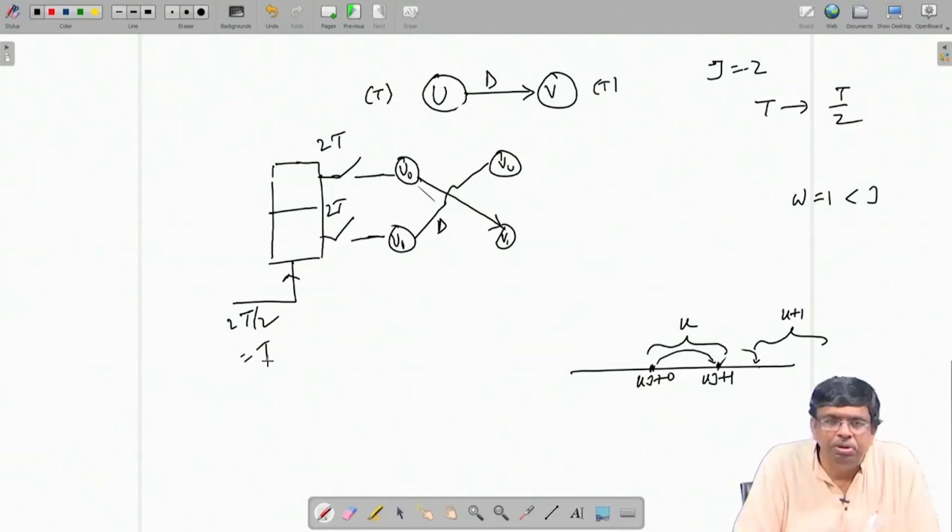So, what have I achieved? I have achieved nothing. Input clock period still remains t. I had first retimed it, it was giving me critical path t. So, input clock period was t only. I say no, I want to make it t by 2. Somebody told, okay, do unfolding. So, I unfolded it by 2 and got something like this, but I find its critical path, because the two nodes are now joining in the same cycle, the delay has gone, there is no separating delay. So, the 2 times get added, t plus t, 2t. Therefore, system clock cannot be shorter than 2t. So, if it is 2t, this is t.